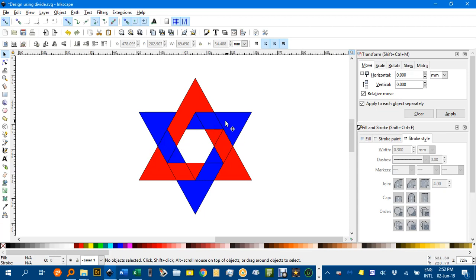Now I forgot to combine them. I should have done it as I went. Click and then shift click and Control Shift plus to combine them all into one object. Control Shift plus, click, shift click, Control Shift plus again. Silly that I didn't do this before. Anyway, if I make this mistake, hopefully you won't.